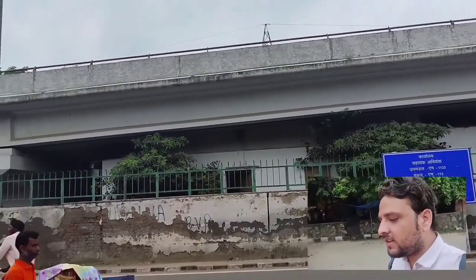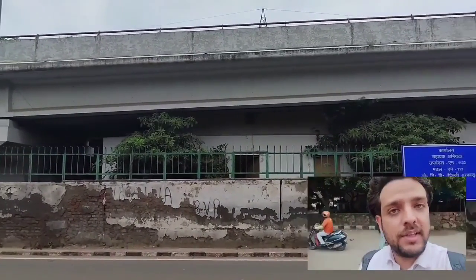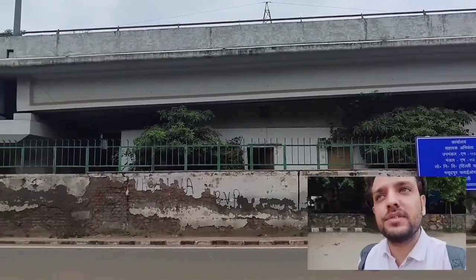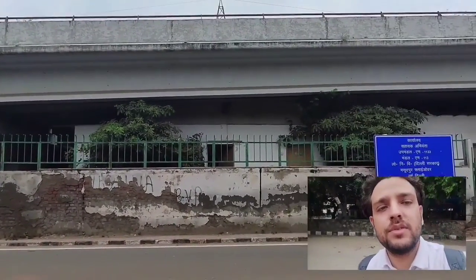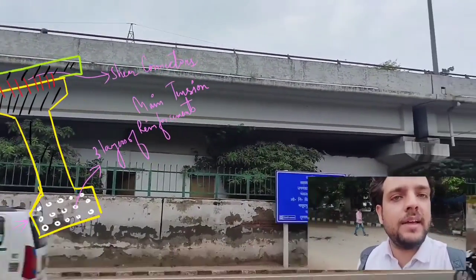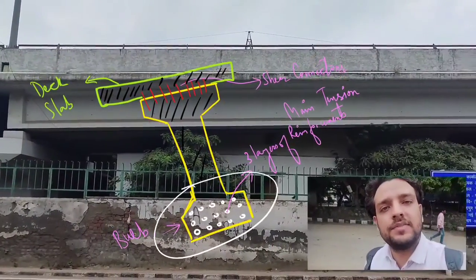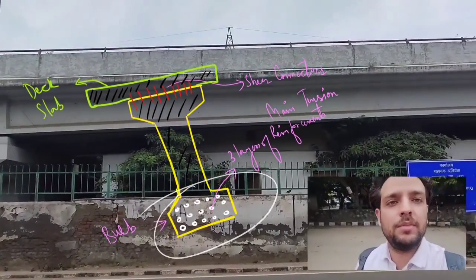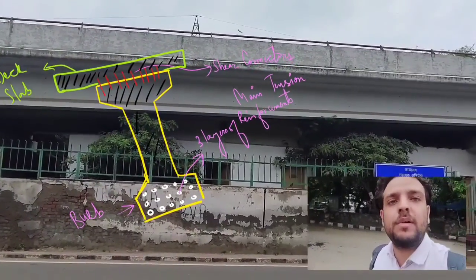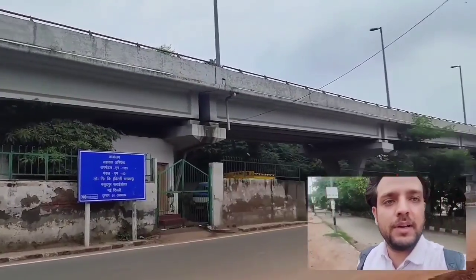So this is another way of optimizing your structural forms by using the knowledge of analysis, where the shear force will be more, where the bending moment will be more. Please notice that bending moments will be more at the mid-range, and there the bulb, this is actually known as the bulb, and sufficient reinforcement is provided at the bulb near the mid zones, which can be curtailed as we move towards L/4, L/8, and so on, providing sufficient development length as well.